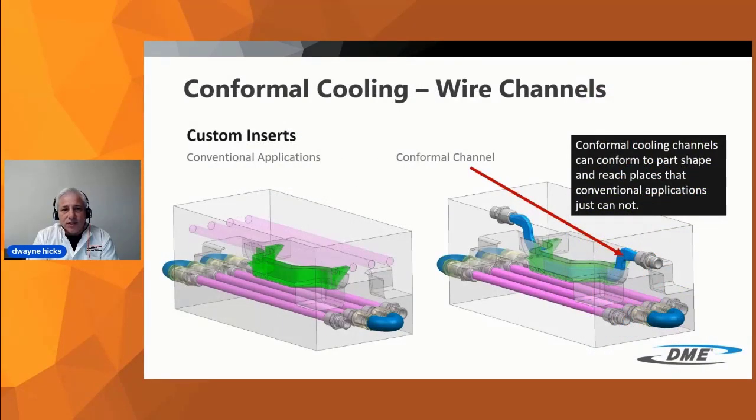It can be very challenging to cool some part surfaces evenly with conventional design techniques. This wire channel model is a good basic example of hard to reach areas. Depending on the size, we could install some cascades or perhaps some baffles, and these methods will obviously help. However, the part surface will tend to be cooler in some areas than others. Conformal methods, being equal distance from the part along the entire length, ensure equal cooling. Anything but perfect cooling does drive up cycle time.